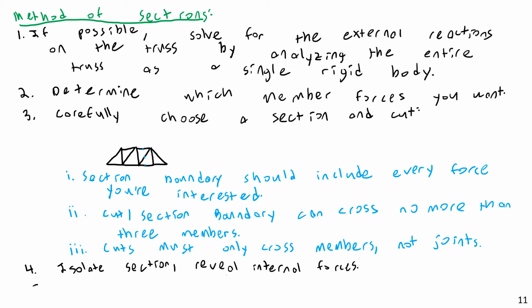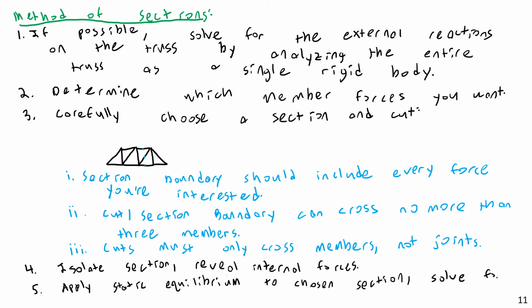And 4, isolate section, reveal internal forces. And finally 5, apply static equilibrium to the truss, to chosen section, and solve for desired forces. Solve for desired forces.